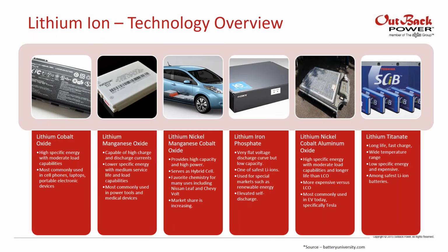Okay, so technology overview. Again, you can see here all the different chemistries that were listed in the beginning. They all have slightly different characteristics, but overall, the advantages of a lithium-ion battery, they have a really long cycle life. Like I said, 8 to 10,000 or more cycles. They have a set capacity, so discharge current does not affect their capacity. And they are slightly less maintenance because you don't have to add water.